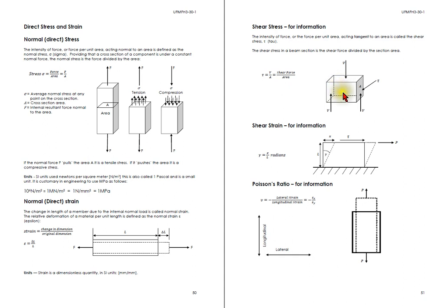Shear force V: V is a symbol commonly used to represent a shearing force. What we've got here is a force being pushed down, so what would that mean in terms of forces on the other side? Well, actually there's a slight error here because this is going to be V divided by 2, V divided by 2. The way to imagine it is that we've just got one V component and another V component. So it's kind of an error in this drawing.